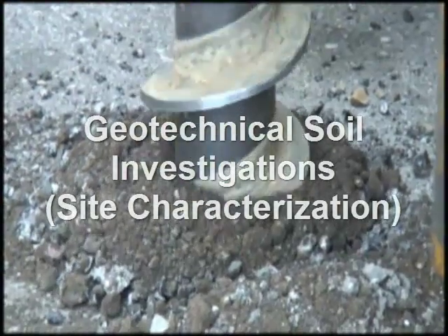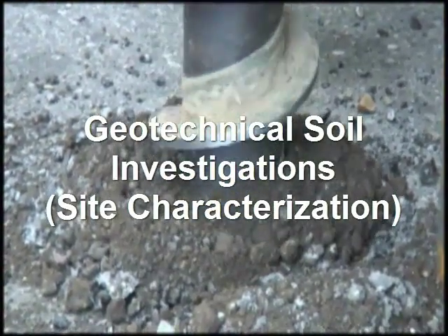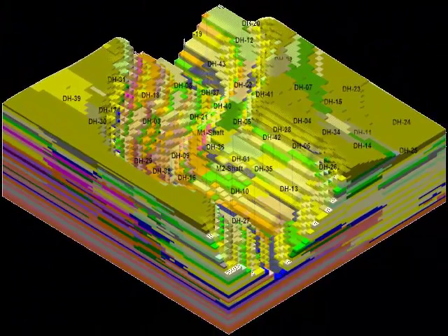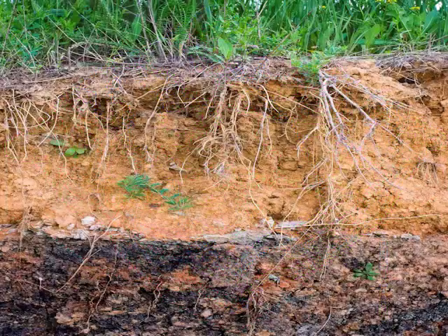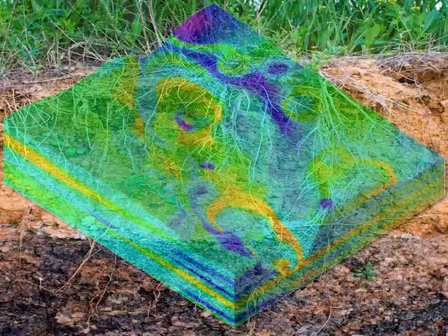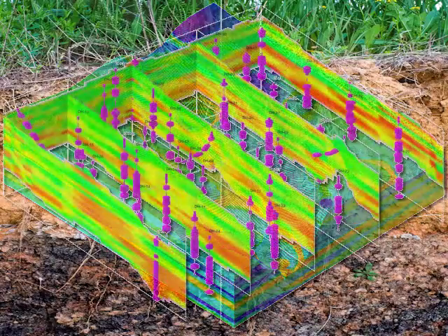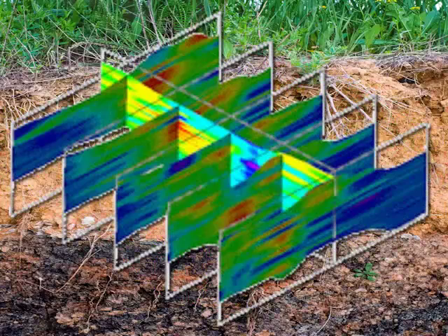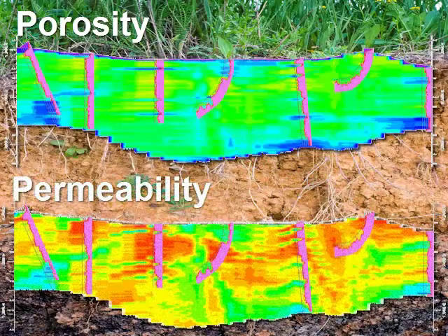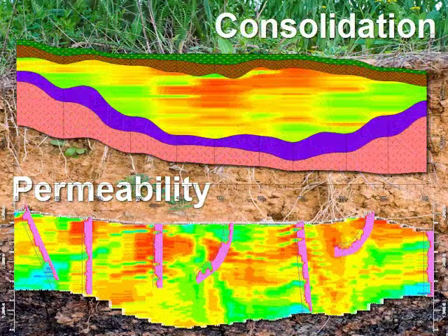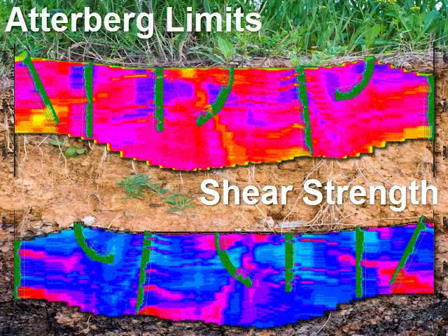Geotechnical soil properties from borings can be numerically modeled, visualized, and quantified in terms of volume and mass. Modeling USCS soil types is accomplished by using the special RockWorks litho blending algorithm. This method allows for discontinuous units that mimic transgressive regressive interfingered lenses. Numerical soil properties, on the other hand, are best modeled using the conventional continuous block modeling algorithms. Examples of these numerical soil properties include porosity or hydraulic storativity, permeability or hydraulic conductivity, consolidation, shear strength, and Atterberg limits.